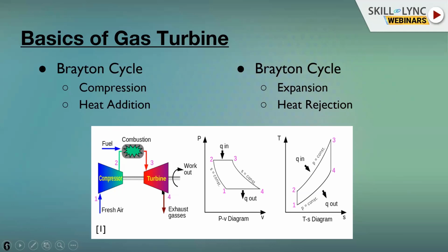So what we are doing over here, we are going to take the heat generated and convert it into mechanical energy or kinetic energy. This combustion generates gases at high temperature and pressure, and they apply direct pressure on the turbine blades, the engine components. In this case, they're going to affect the turbine blades. These blades extract the energy from the high pressure and temperature gas and then rotate the shaft coupling, which in turn will rotate the generator. So this 3 to 4 step is given over here.